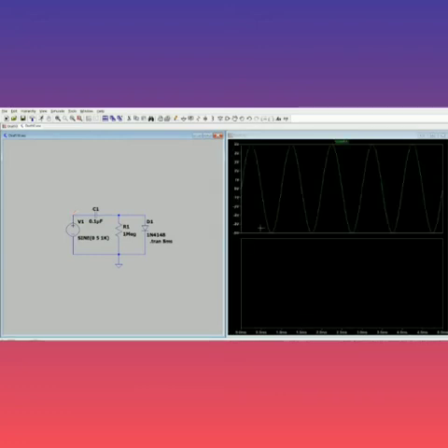So now we can see that the input sine wave occurs. So I've given the amplitude as 5. So the amplitude of positive 5 volt and negative 5 volt, my wave has come. And I also have given the stop value to be 5 millisecond. So for one complete clock period, I require 1 millisecond. So here 5 complete clock cycles are there. So it requires 5 milliseconds. That's why I've given 5 millisecond in the stop value.